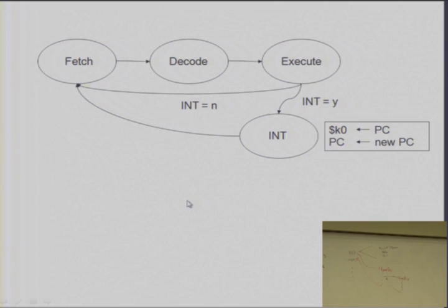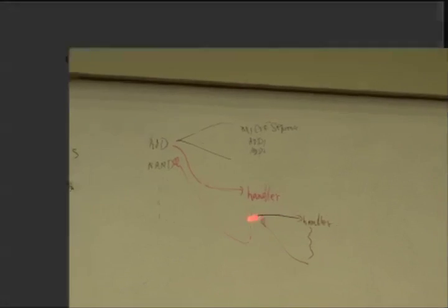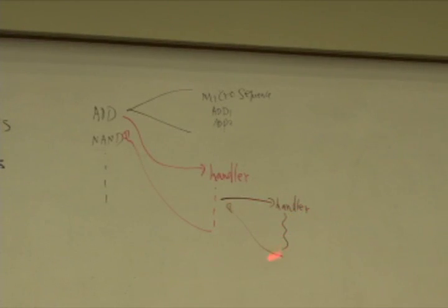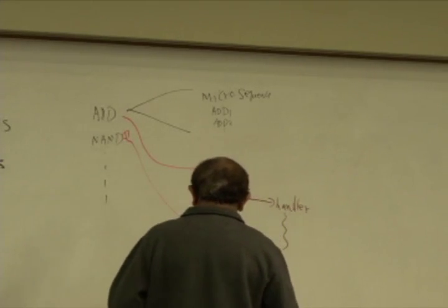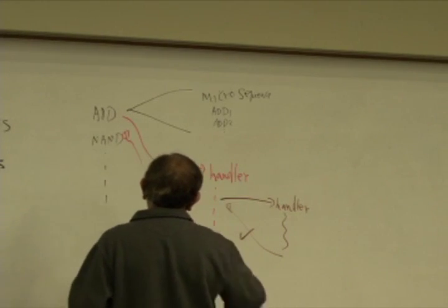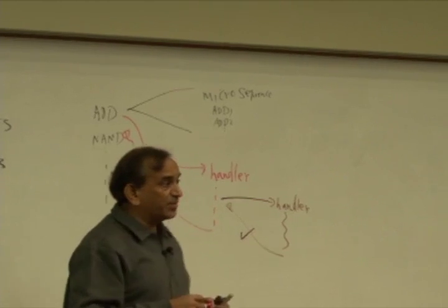This register, right? There's only one register, and what we've done is, when we go to this handler, I've modified the K0, right? And then I go off again. In the middle of this handler, there's another exception, or interrupt, or a trap, and I go off to another handler, and now I've lost the original K0, right? So I would never be able to go back. I can return here, that's no problem, but I cannot go here, because I've lost my K0.